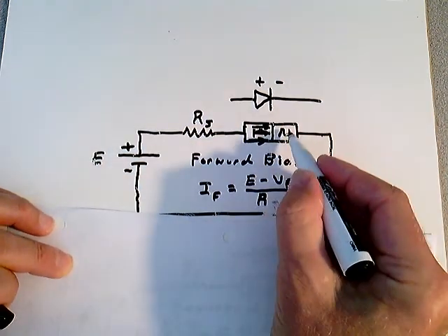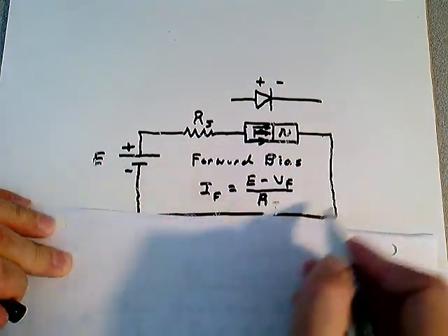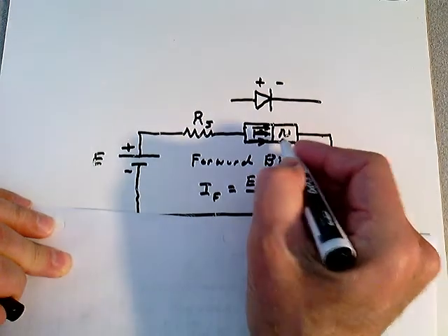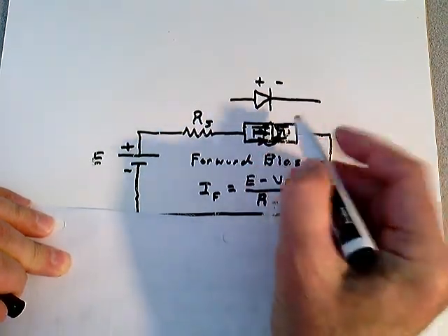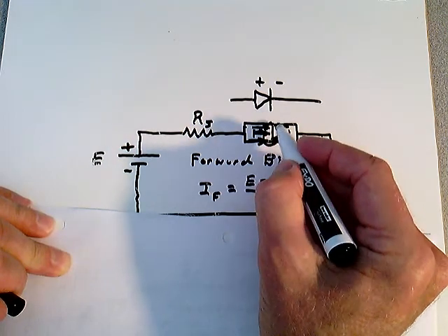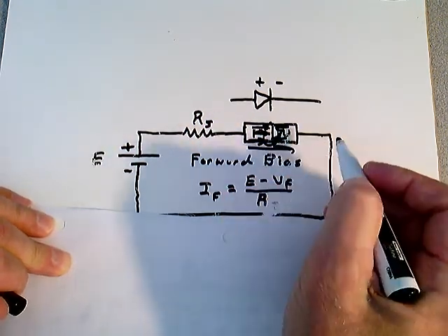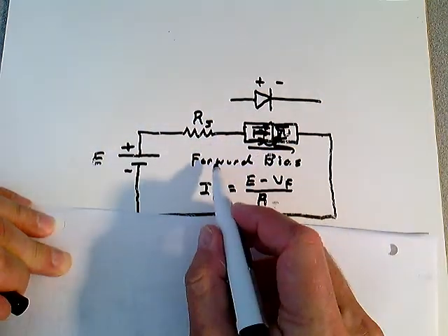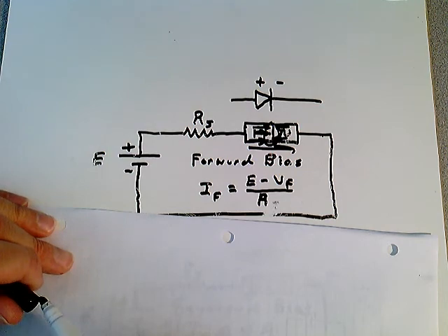And over here you have negative material, which is electrons, and you have negative down here, so they repel each other, and these negative charges push these into that junction, and this junction gets reduced. This depletion area in here gets reduced. It gets very, very thin, and that allows for current to flow. That's why you get, in a forward biased form, the diode conducts current.